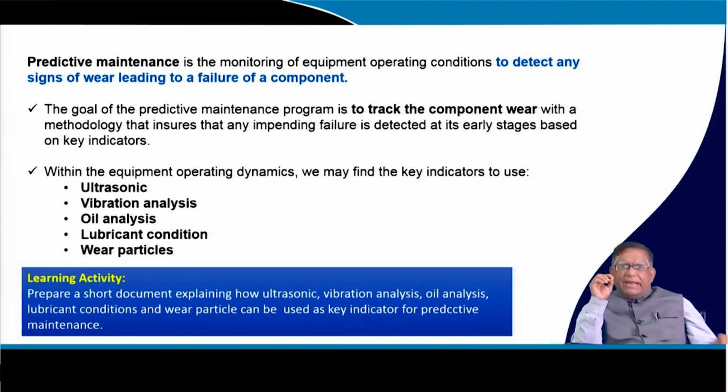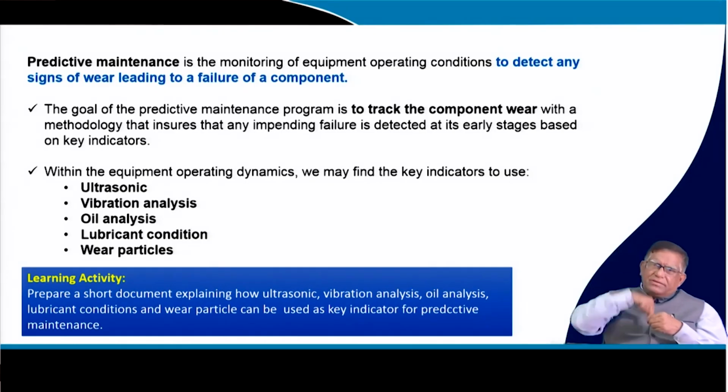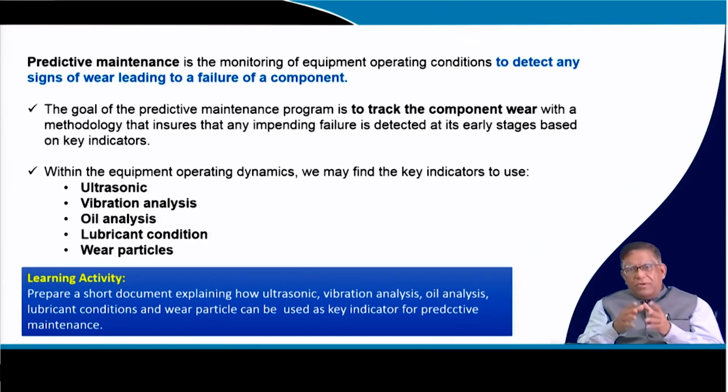So you will have to get some key indicators, to know where any malfunction or failure is. There are certain tools. Doctors test these things with a stethoscope, and they have a thermometer. Similarly, as an engineer, if your machine is ailing, you will also need your thermometer. You have heard that nowadays they put a catheter inside and take images. The same thing is called a boroscope.